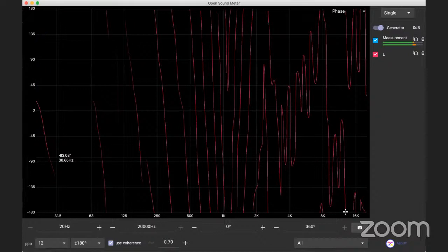For SPL, a whole SPL calibration will be done. Unfortunately, Open Sound Meter does not have it. You need two extra things for it. You need a proper FFT which has the SPL calibration tool in it, and you'll also need the SPL calibrator. You're supposed to push a microphone into the SPL calibrator, turn it on, turn up the right gain, and then set up that calibration inside Smaart or System. And so the moment System or Smaart knows what 94 dB SPL or 110 dB SPL is, it'll do an SPL measurement over that, comparing it to that gain setting that you have given.